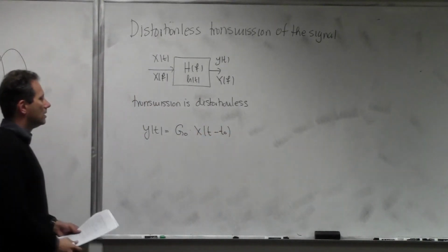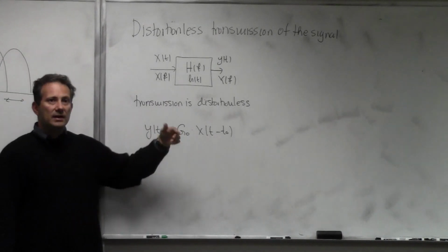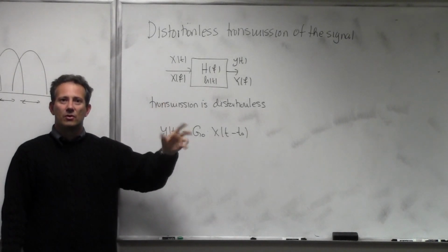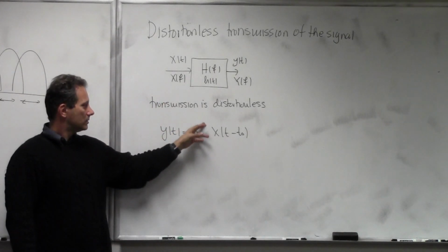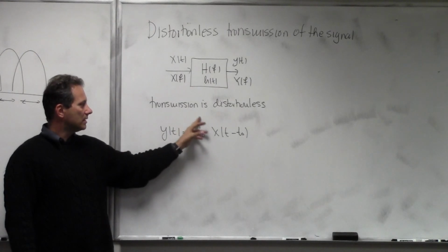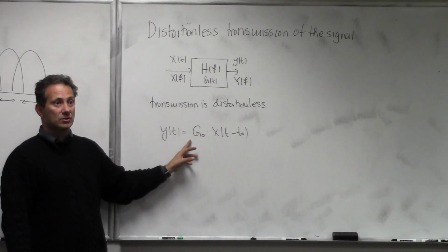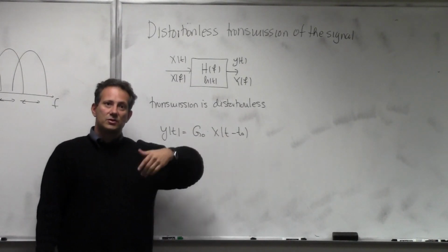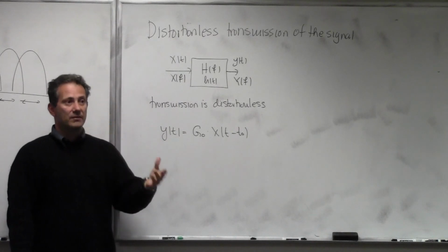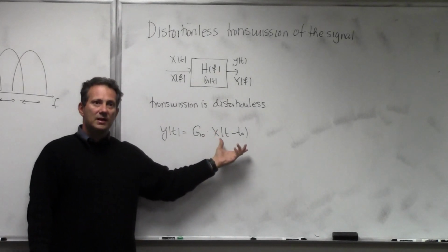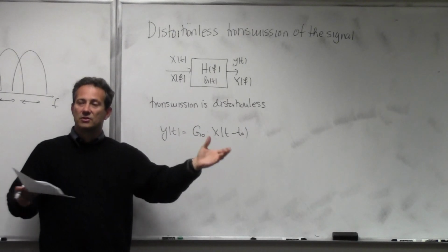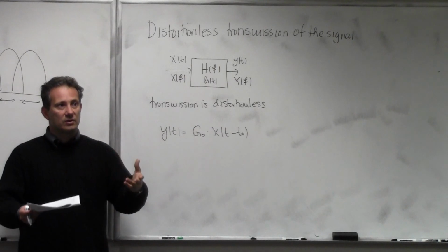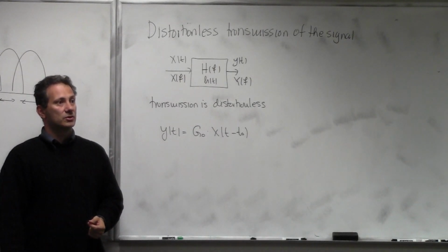In other words, if there is some scaling of the signal, I'm okay with that, because I can crank the volume up or lower the volume. So I can assume that the gain does not introduce any distortion to the signal. And also, I'm going to allow a delay, because the signal travels long distances or short distances, whatever the distance may be. If there is a delay introduced in the whole signal group, I'm going to assume that the signal is delivered to the reception point without any distortion.